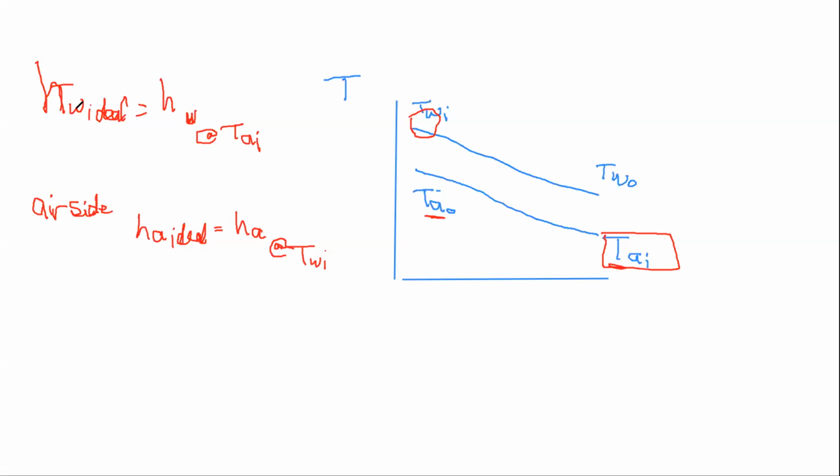For water, it's going to be cooled down, so the ideal case is the lowest temperature in the whole system, which is this. Air is going to be heated up, so the maximum temperature air can reach is this. It will not reach this value, but we are doing a comparison between the actual change of enthalpy and the maximum one. The maximum is the maximum ever; to realize it, we need an area equal to infinity. But it's one way to see how effective this unit is performing. For packed bed humidifiers, we expect an effectiveness in the order of 70% or maybe 80% at most.